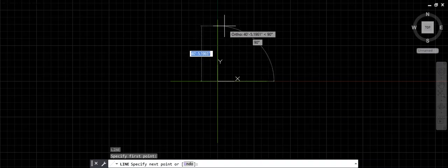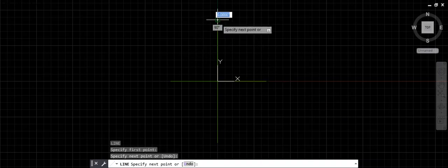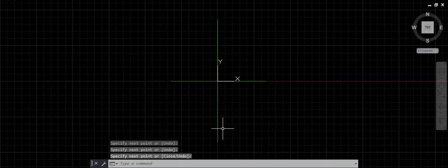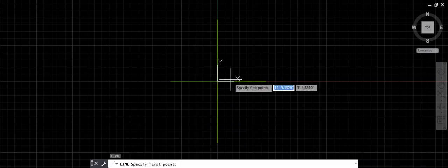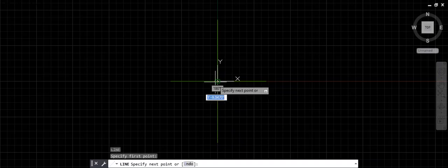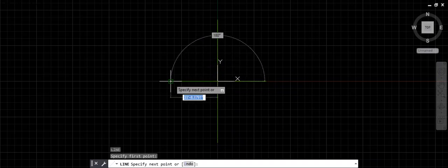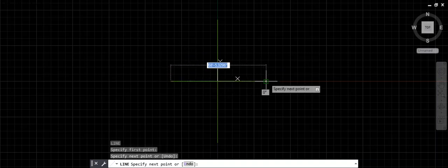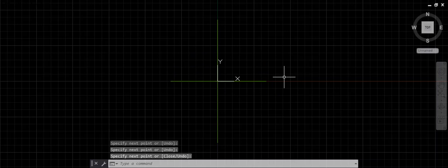We simply generated a 90 feet line from the 0, and a 180 feet line down. Enter. And this is your y-axis, and the x-axis has to be drawn approximately 30 feet to the left and 66 feet to the right. So this is your x-axis.